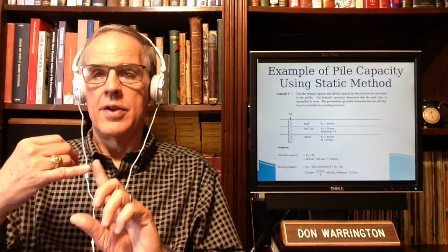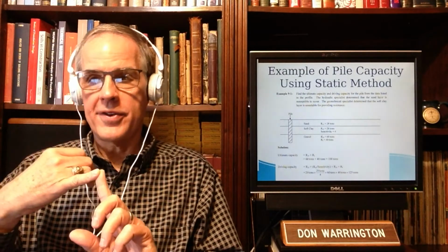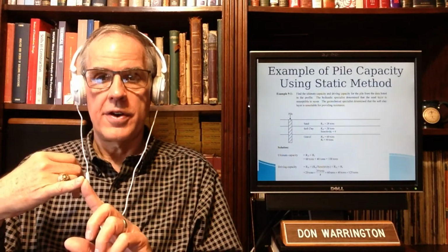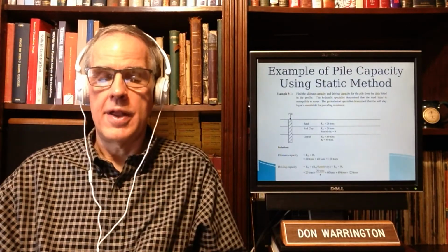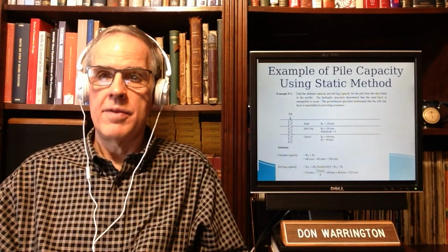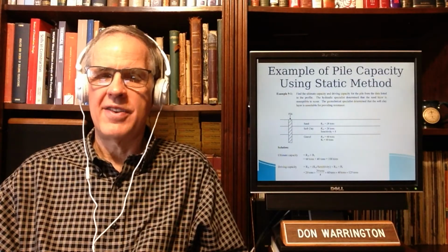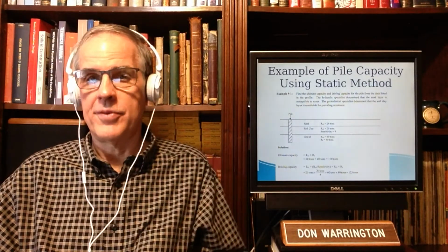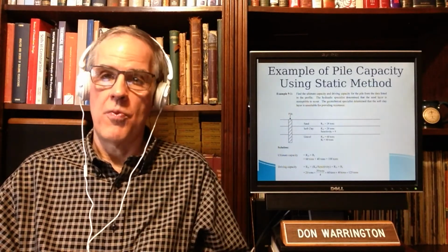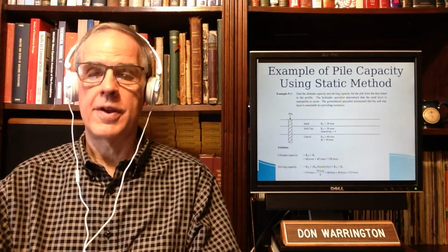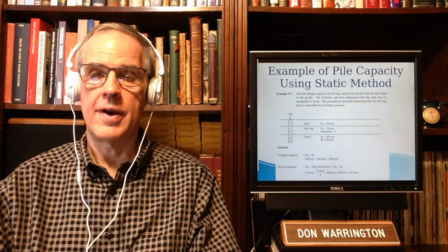Therefore, what we call SRD, which is soil resistance due to driving, is different from the ultimate capacity. They don't necessarily have to be the same. In most decent stratigraphies they are, but there are some like this one where they're not. So we have a different value for each. You have to be careful about that when you're designing driven piles.